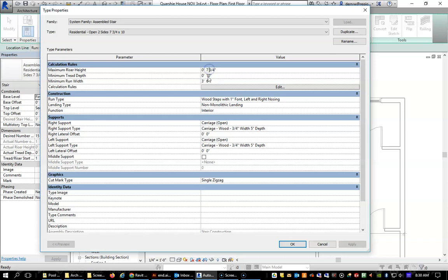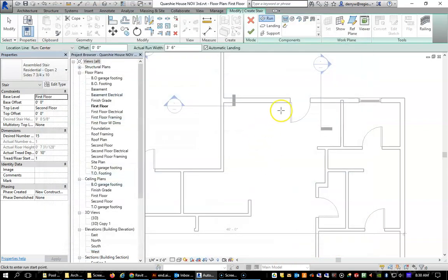If you haven't already changed these values, you would duplicate that, rename it, and call it this new value. And these I think are more typical. The default in Revit is going to probably create one or two extra treads, which is going to consume some space in your house that you probably have not allotted for. So go in and change these if you haven't done so already.